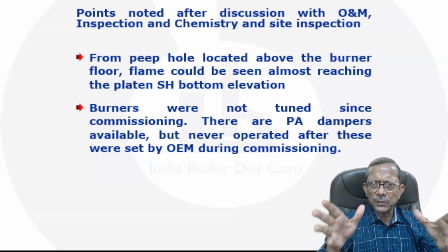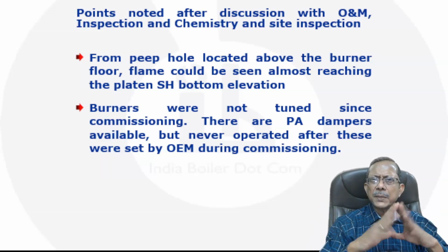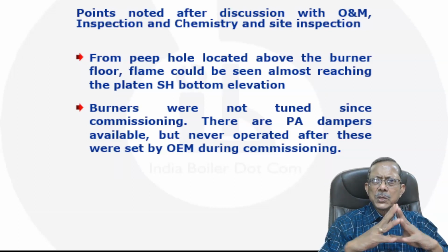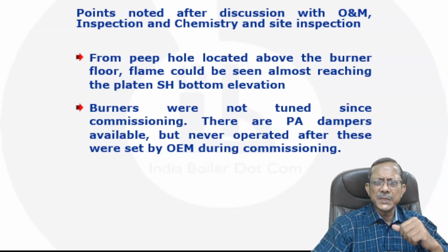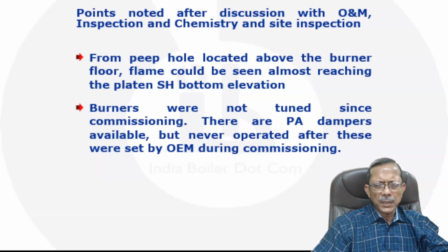I asked them when they had operated this damper, and they said they never touched the damper at any point of time. Okay, so that is another problem, that combustion was not due. And since the flame was scattered and long, naturally another doubt comes, because these are FO flames which you can see: whether there is a problem with the atomization, or some amount of dirt coming with the fuel, or whether water is coming with the fuel, right?